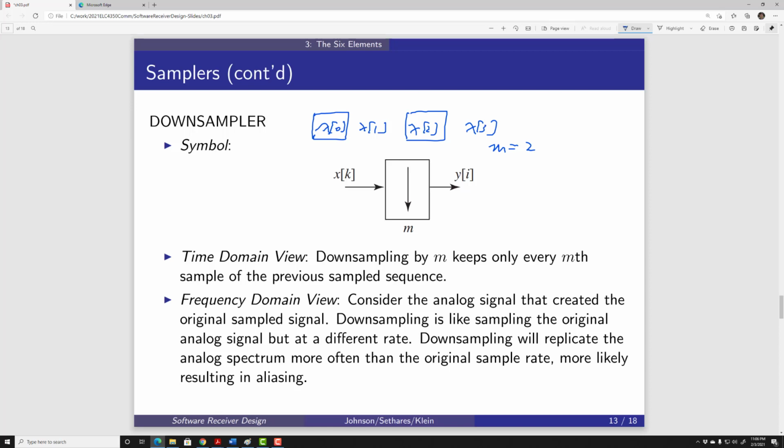From a frequency domain view, what we did is change the sampling frequency. Therefore, an effect called aliasing may occur. From the sampling theory, we know that if the signal looks like this in the frequency domain, here is 0, and here is the maximum frequency in my original signal, let me call that Fm. The Nyquist rate tells us if I sample with a sampling frequency Fs greater than or equal to twice the maximum frequency, then I do not have any aliasing effect.